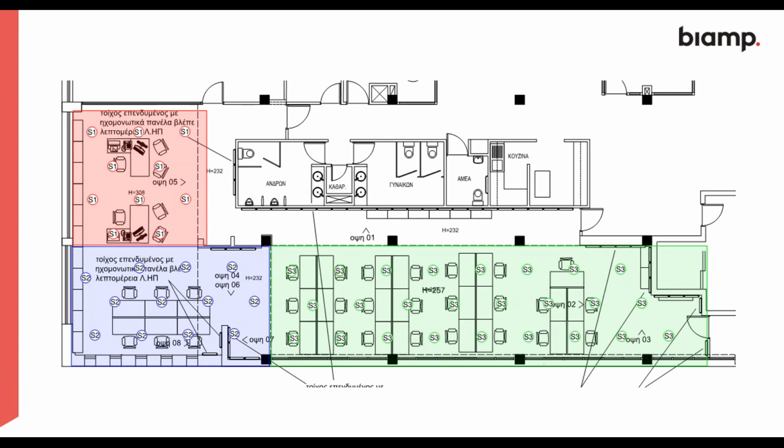Question here: if one of the emitters fails, does that mean that the zone will not be working? That can mean one of 2 things. It depends on the fault that's caused it. Sometimes you may lose everything from the faulty emitter onwards, or you may lose all the A's, for example, or all the B's. What I will say is 90% of faults on systems are caused by cabling errors, so it's normally the cable connection.